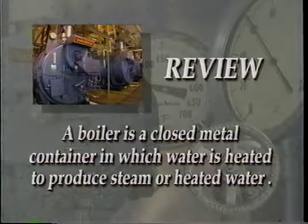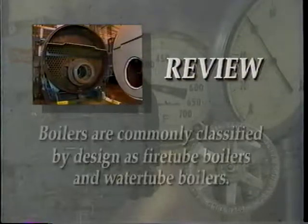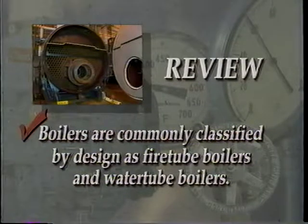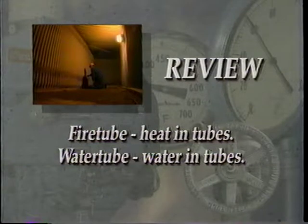Review. A boiler is a closed metal container or vessel in which water is heated to produce steam or heated water. Boilers are commonly classified by design as fire tube boilers and water tube boilers. In fire tube boilers, heat and gases of combustion pass through tubes surrounded by water. In water tube boilers, water passes through tubes surrounded by gases of combustion.